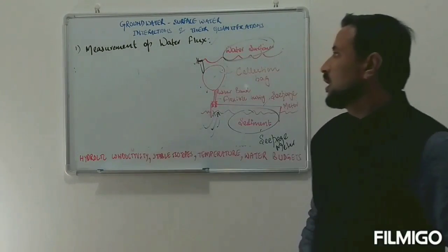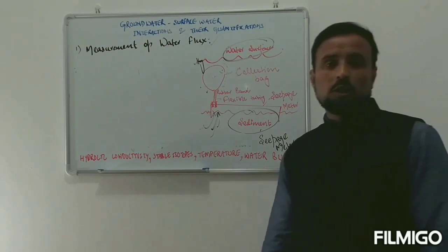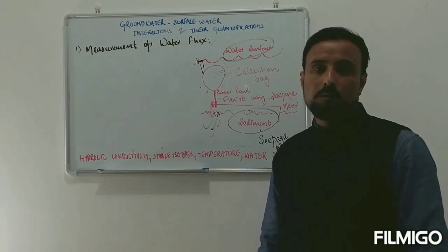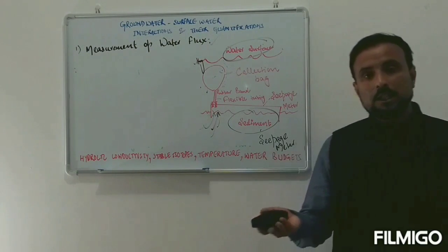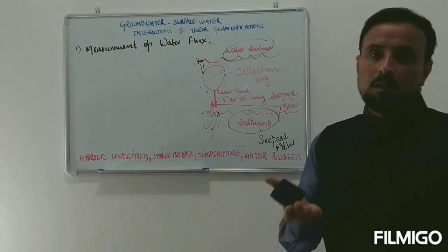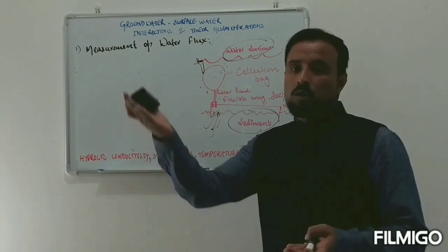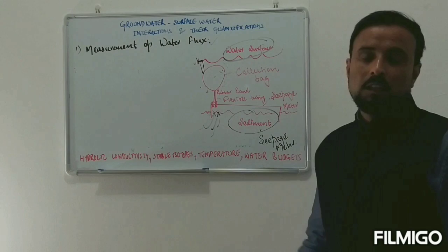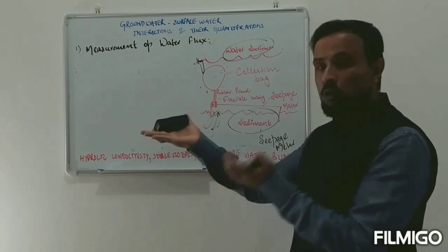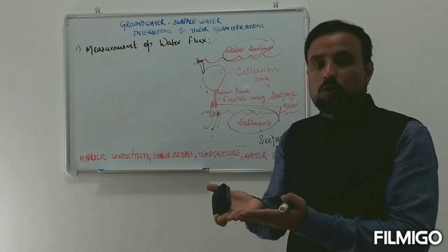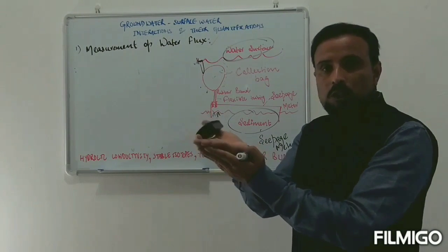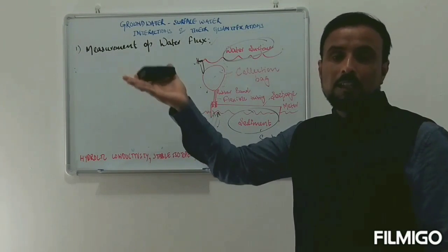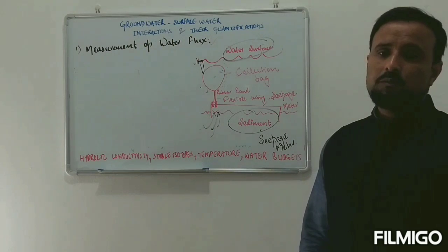It can be used to quantify the groundwater and surface water interaction, but not all the time is this approach useful, because it is assumed that all the groundwater supports the surface water, but this is sometimes not true, because there is also a hyporheic zone. The hyporheic zone is a zone between groundwater and surface water, basically a mixture of the two. Sometimes the hyporheic zone also supports the surface water, and that cannot be measured by seepage meters.